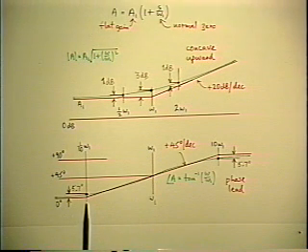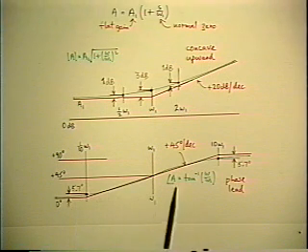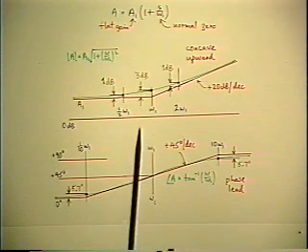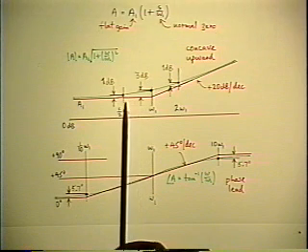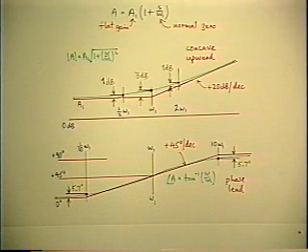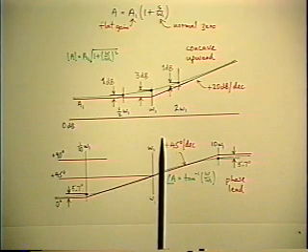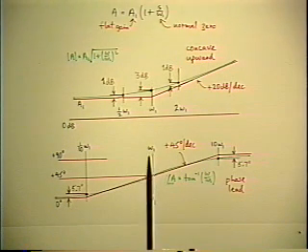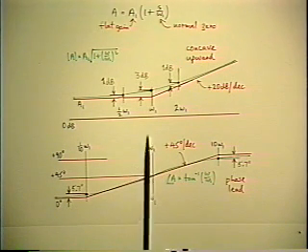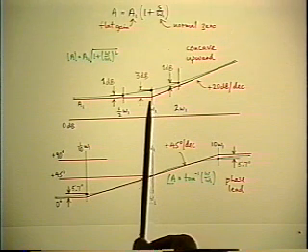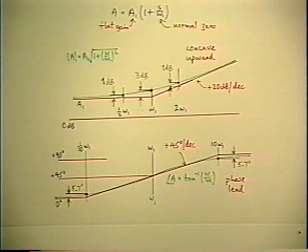Obviously you begin to see it when the asymptote changes slope. But that's a whole decade below the corner, which is much further away than the octave on the magnitude graph. So the bottom line of that comparison is the influence of the corner frequency extends a decade above and below the corner in the phase graph, and it only extends an octave above and below the corner in the magnitude graph.